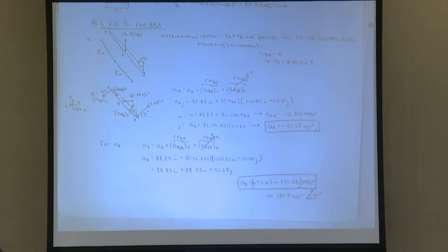If you're given angular velocity, you would find the translational velocity at the point, and since that's the same on both, you'd relate it that way. Find the omega of whichever one you didn't know anything about, and then you can find the velocity at the endpoints. You're basically just inching your way along it.